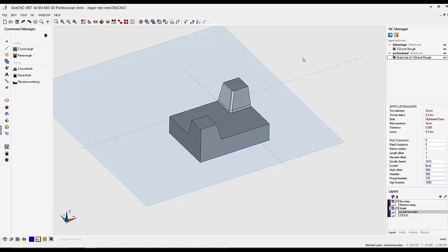Quite a small component. You imagine the savings you could make on larger ones. It also utilizes your tools a lot better. You're not going into full area contact on the tool. You've permanently got 20, 30, 40% radial engagement, whatever you program. And you've got a 30% saving straight away. So obviously increasing the capacity of your machine.